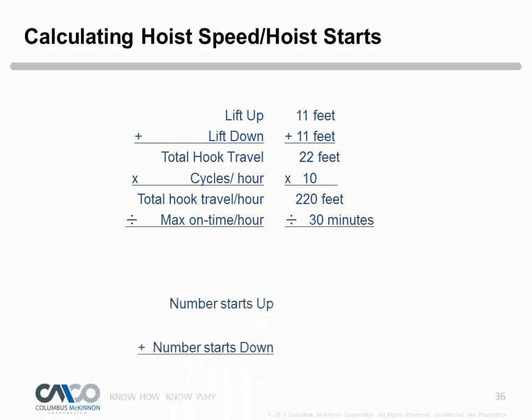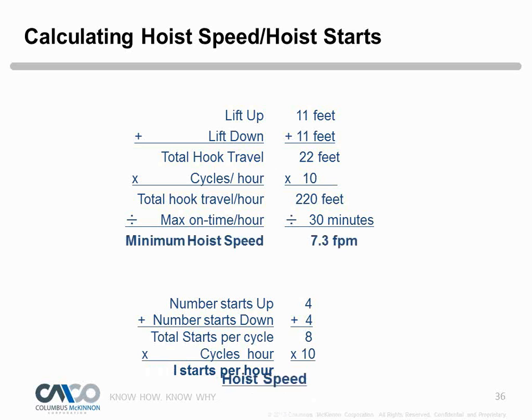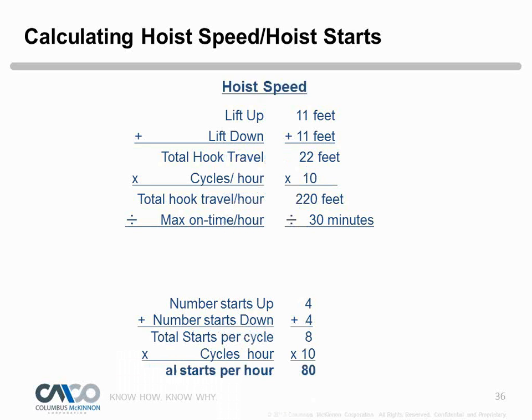And then what's the number of starts and stops? We do it 8 times per cycle, and we do that 10 times per hour. So the total starts per hour is 80. So we're not exceeding that 300 in that case.